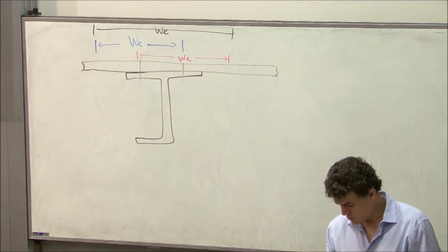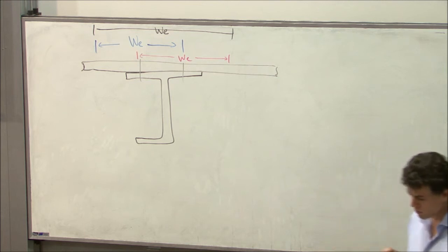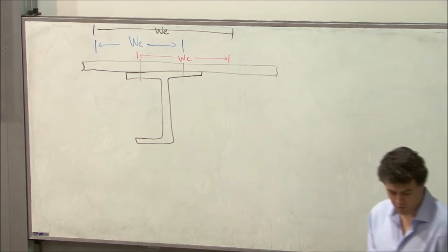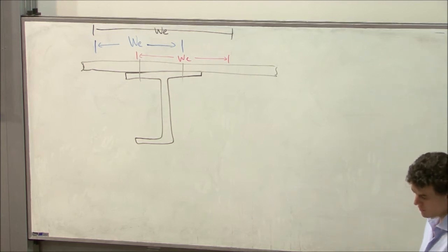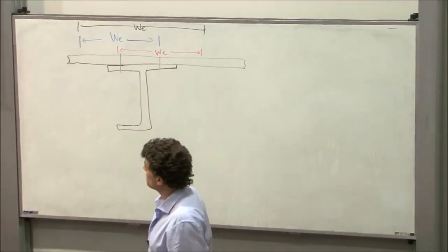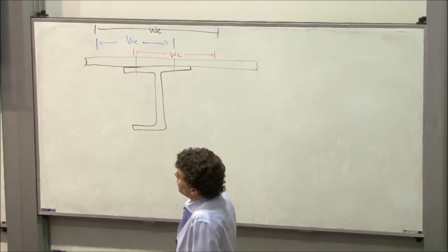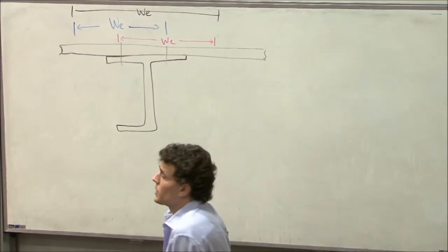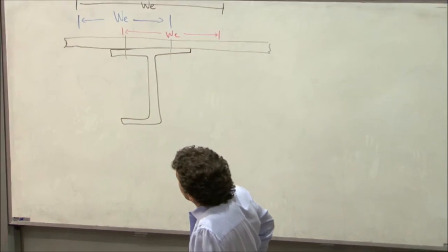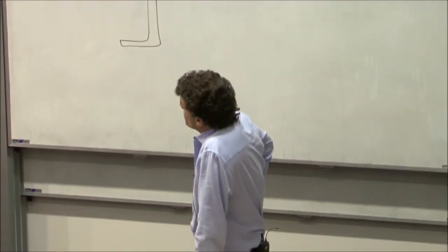So let's do an example which we will use again in a minute. Hopefully you can read the dimensions here. If you can't, I can read them out. But we have a Z stringer on a bit of fuselage skin, and the skin thickness up there is 0.05 inches.